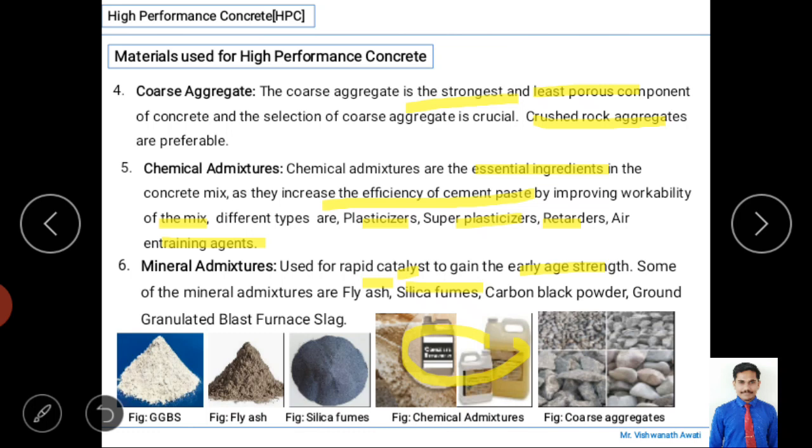Now here it has a disposal problem, right? The problem with fly ash is disposal, because it was earlier considered a solid waste. And in construction we require cement, but cement is not eco-friendly. It has emission of carbon dioxide as well as heat. So we are reducing the cement content requirement, as well as solving the problem of solid waste. So we are using fly ash.